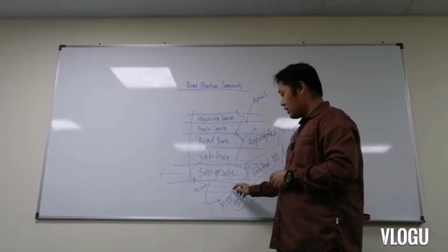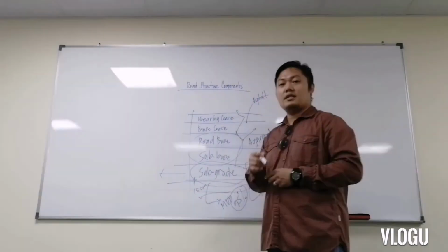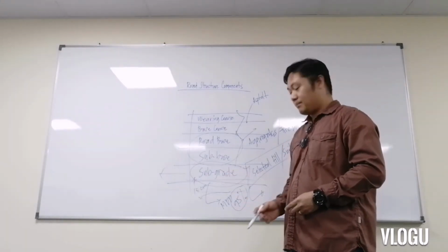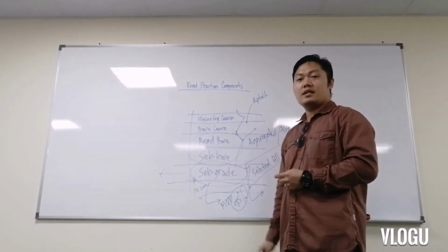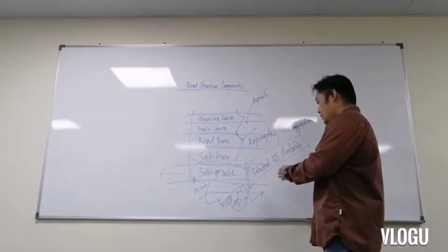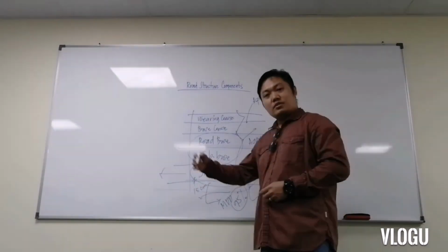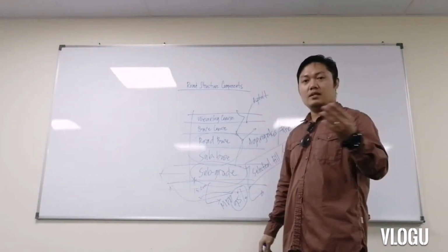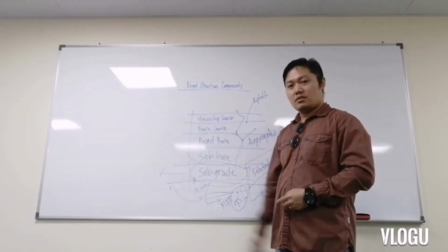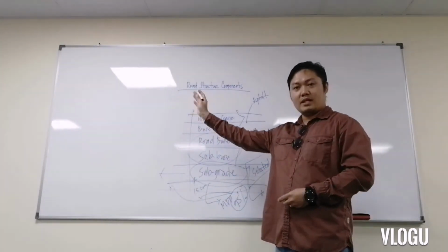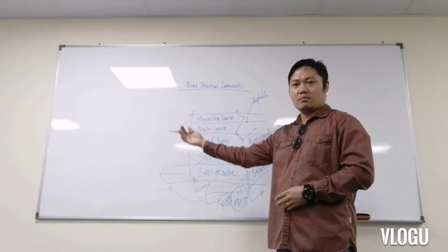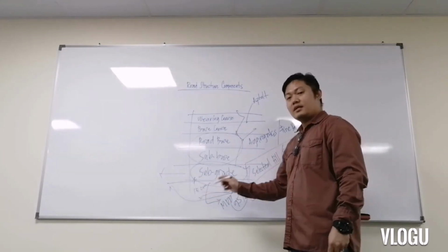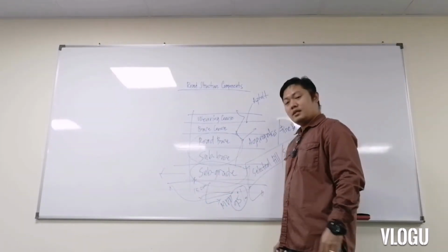In order to correlate, we are going to conduct the field density testing by means of nuclear gauge, and at the same time by means of sand replacement method. We also have to conduct the CBR testing. On site, there are two types of CBR. We have the in place, and then also the soak CBR. Soak is from the sample taken to the laboratory and conducted in the laboratory, and the in place CBR is done on site after the compaction.